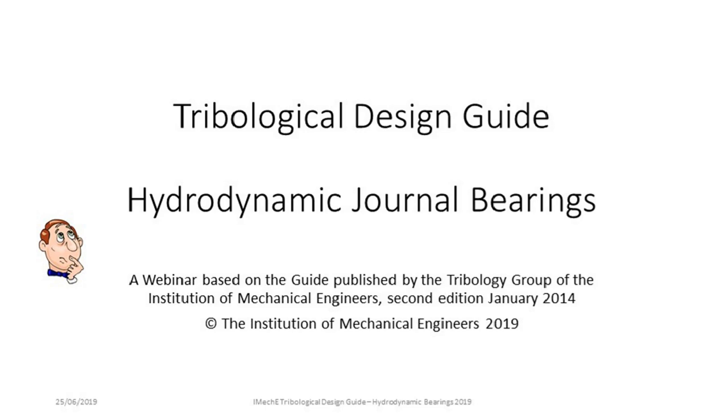The first port of call when you want to reduce these losses is to reduce the viscosity. But there are costs associated with that. In terms of lip seals, I don't know how much of the loss comes from, as it were, solid contact. The whole object, the exercise, is to stop the fluid getting out. So part of the absorbed torque must go into effectively solid contact between the polymer or elastomer and the solid surface, I suppose.